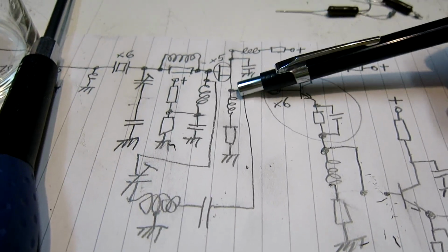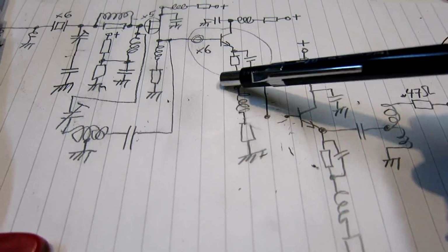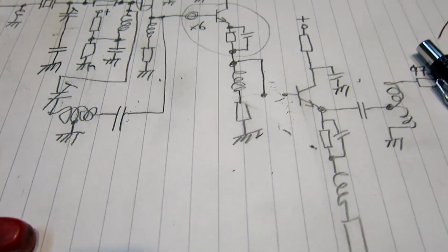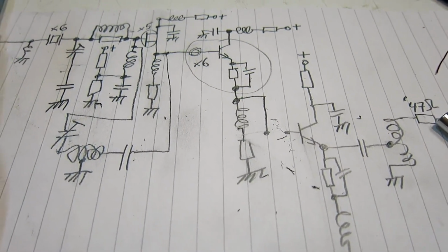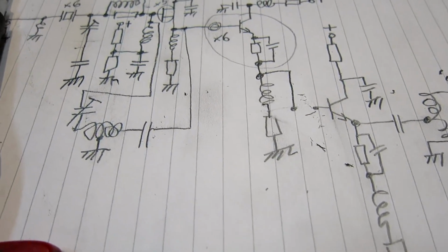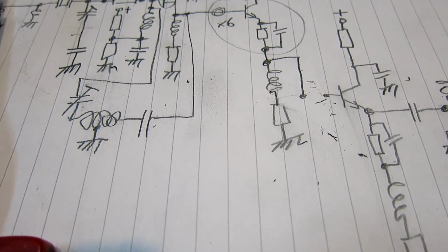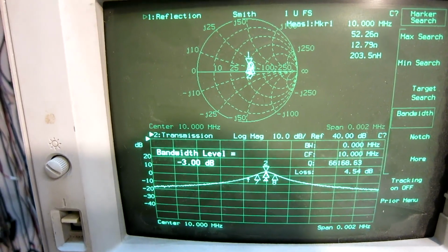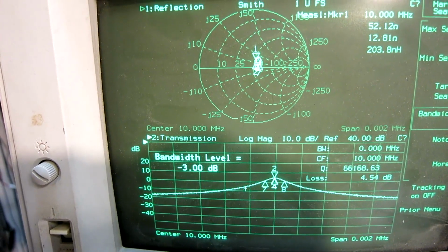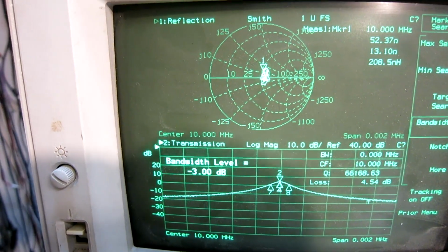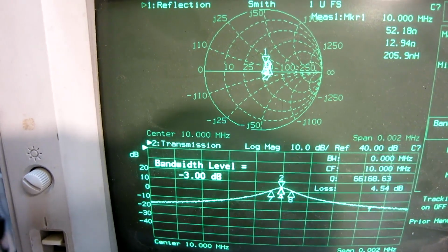I have reconnected here and disconnected here. Note there was a drawing error I have corrected here. And then the impedance at this point is extremely low. So I put the 47 ohm resistor in series with the cable to the output connector. This has not changed the frequency response at all. Obviously, the emitter follower shouldn't change the waveform as long as it's not very heavily loaded.